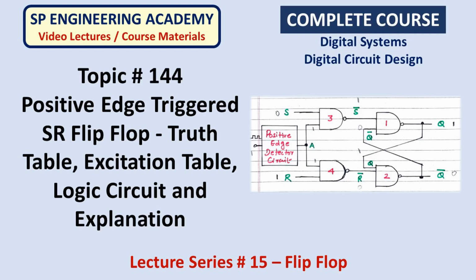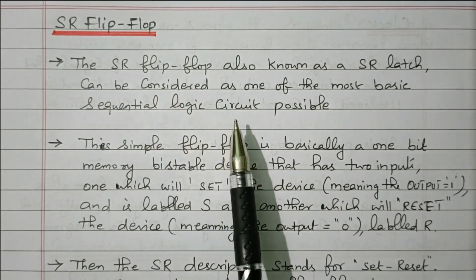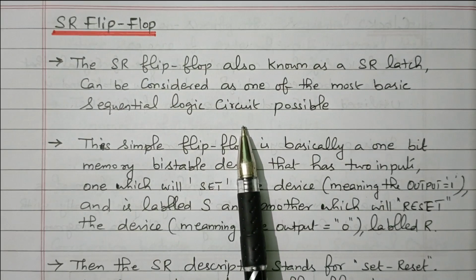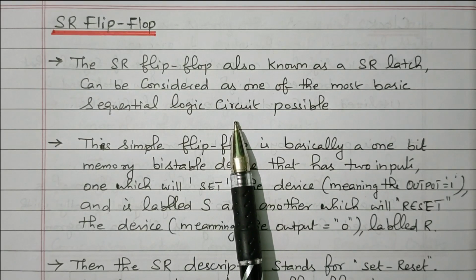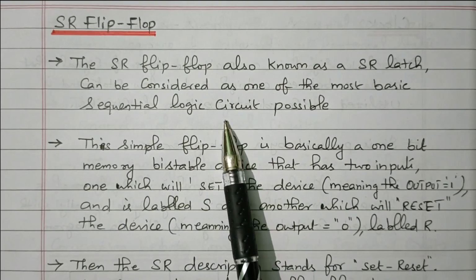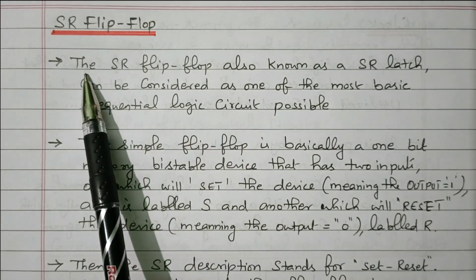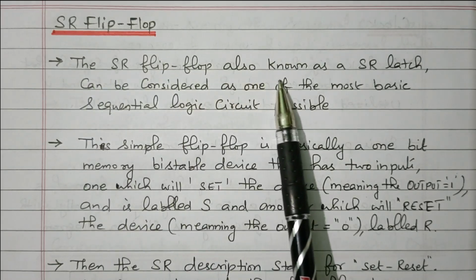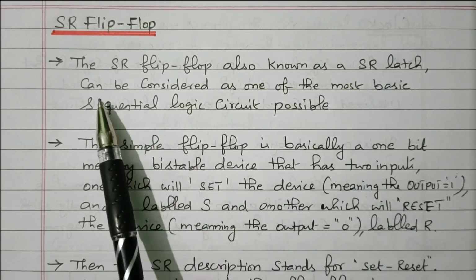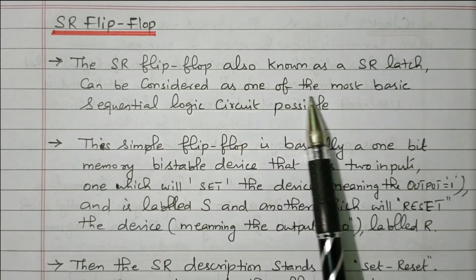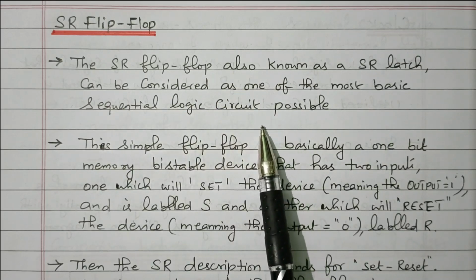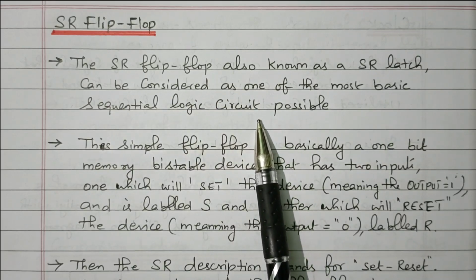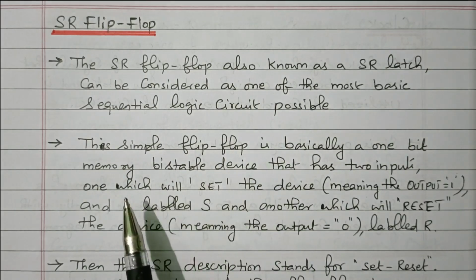Now we'll go to the topic SR flip-flop. We know that a flip-flop is a storage element. The output depends upon the input as well as the previous state of the output. The previous state of the output and the input will decide the output. Now we'll see this SR flip-flop. The SR flip-flop, also known as an SR latch, can be considered as one of the most basic sequential logic circuits possible. So the SR flip-flop is a very basic type of sequential circuit.